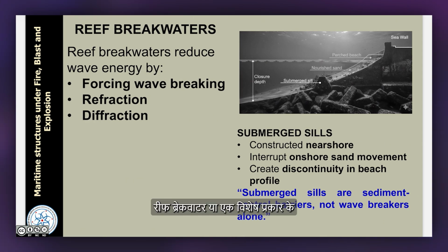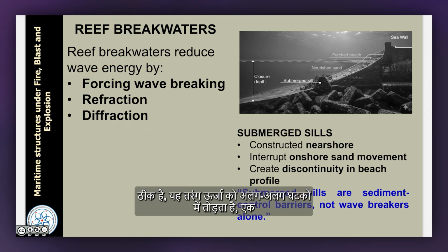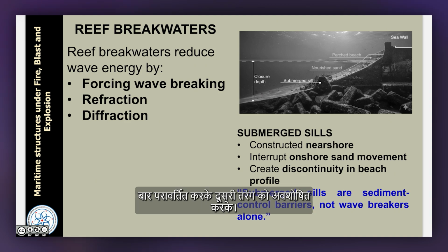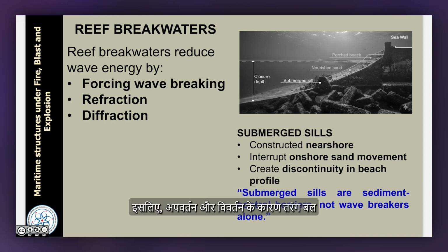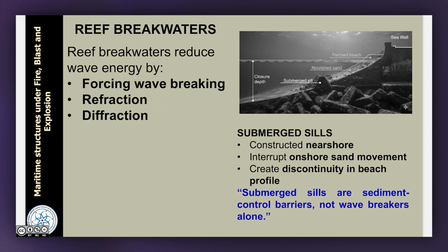Reef breakwaters are a specific kind of breakwater, constructed near the shore to reduce wave energy by forcing wave breaking, inducing refraction and diffraction in the waves. Okay? It breaks the wave energy into different components. Once by reflecting, second by absorbing. Therefore, the wave force is broken and the amplitude is reduced by refraction and diffraction.